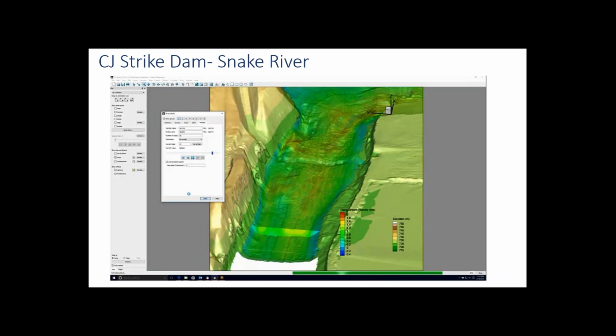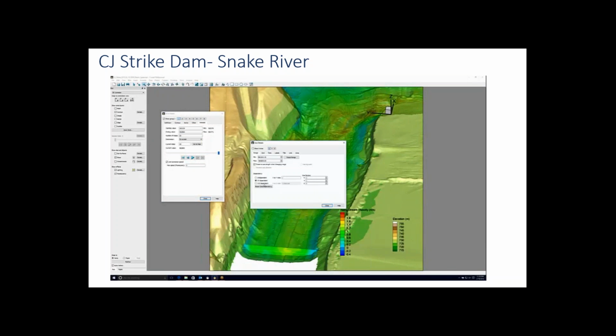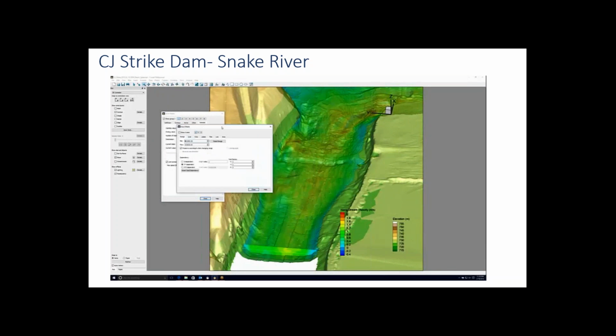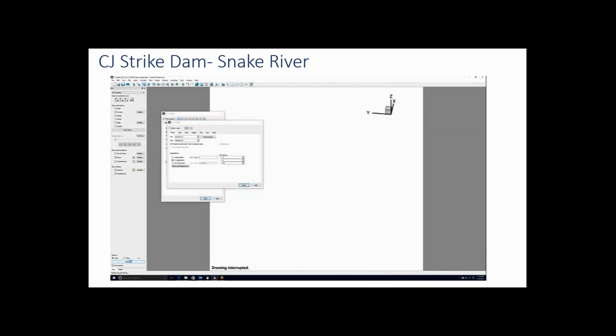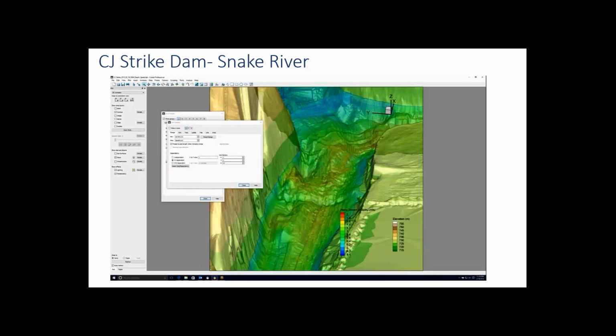It'll be your left looking at it, upstream of that. We're now doing slices perpendicular to the flow, and so just through the 3D field coming up with slices that we can look through and visualize in more detail what the velocities are doing. And as you go through the slices, I believe we'll run through this another time, but you'll notice near that scour hole some very high velocities. So you're starting to see the interplay of the water, the hydraulics, and the stream bed.